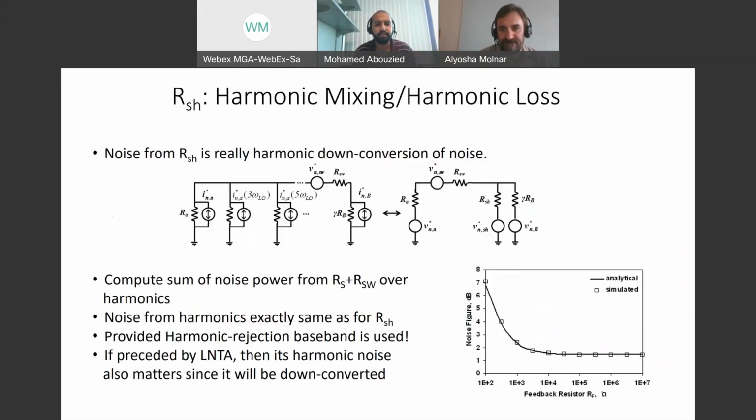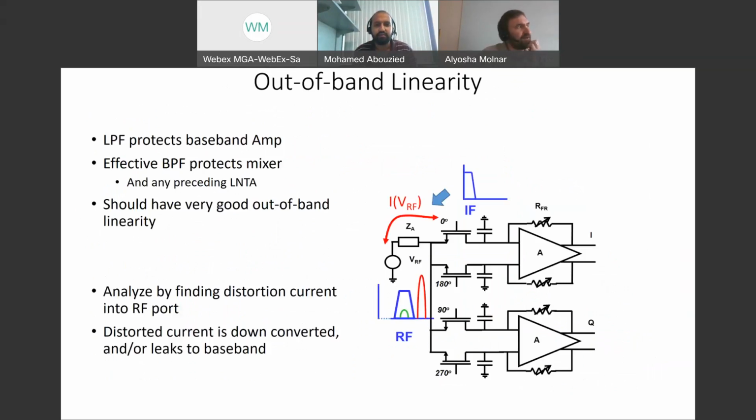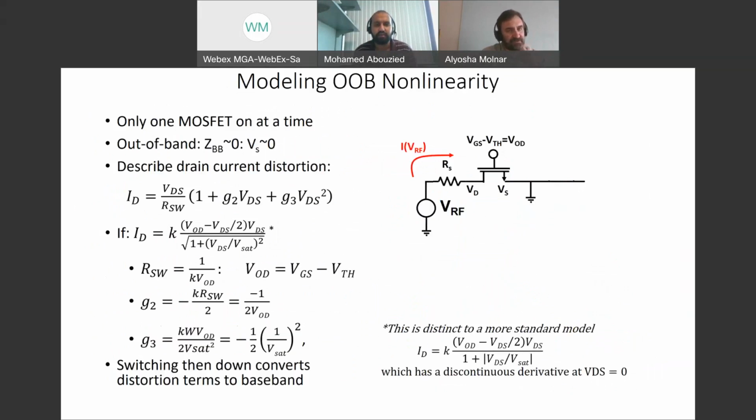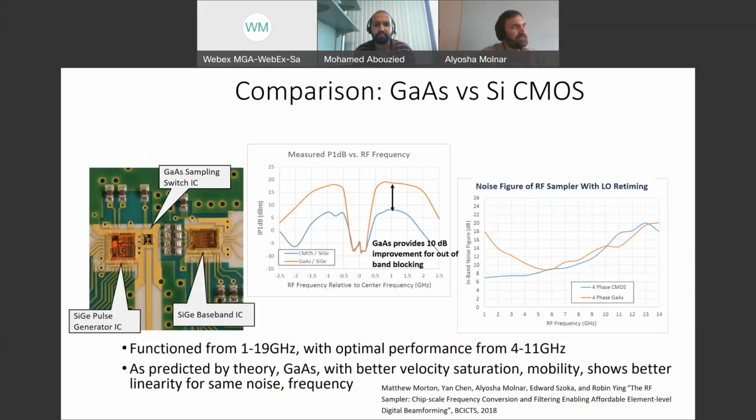And what is the effect of the number of phases on this offset? That's a good question. It depends. If you don't have overlap, which I will talk about, then it's not a huge effect, except that it can allow for a higher Q filter effectively, because it raises the upper bound on the in-band impedance, and then that will have an interaction. So if it's higher Q, then it will shift more for the same amount of parasitic, or it'll appear to shift more. But I haven't at least seen a super strong effect of having more phases. It's not the dominant thing.